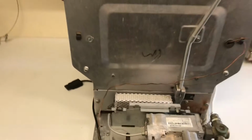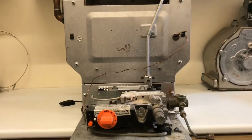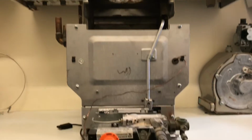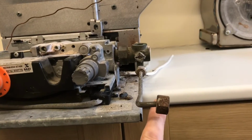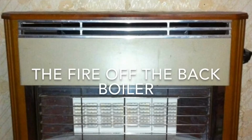A back boiler again is an open flue appliance, and again an open flue appliance gets its air for combustion from within the room. So how does a back boiler work differently from the floor standing one? Well, basically this would be behind the fire. So this pipe you can see here, that would be attached to the fire.